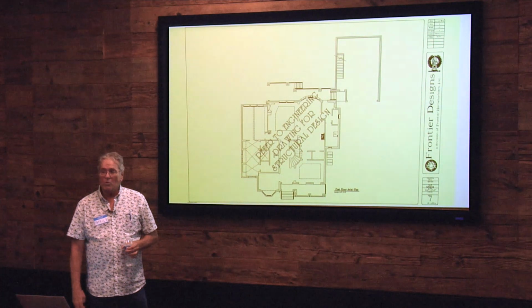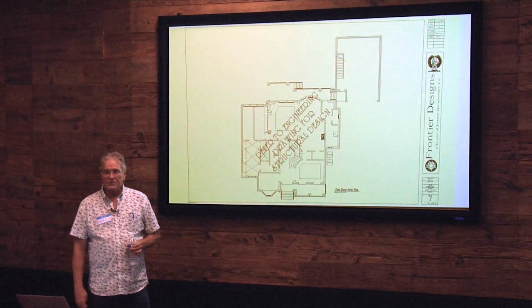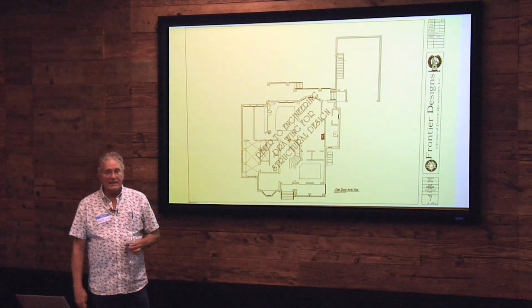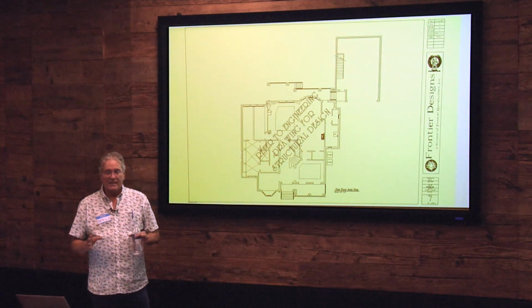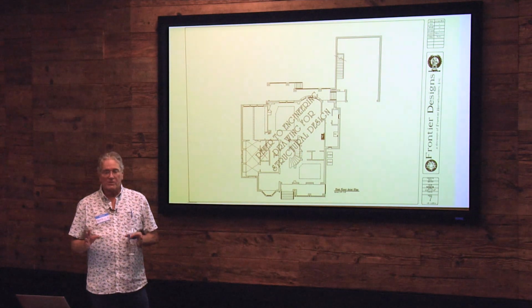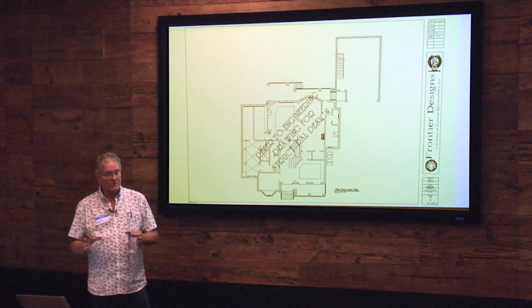If that's something you want, tell the designer to draw it on there. Once it's on the plan like that, it will tell everybody that's starting the work that, hey, eventually there's going to be this vent running through this direction, so pay attention. It may not speak so much to the trade that's working, but to the person doing the project management. They want to keep that in mind.